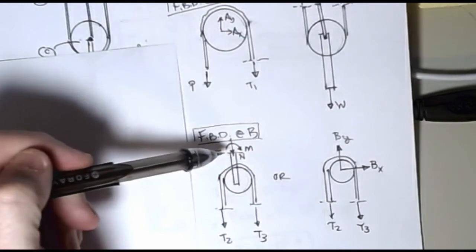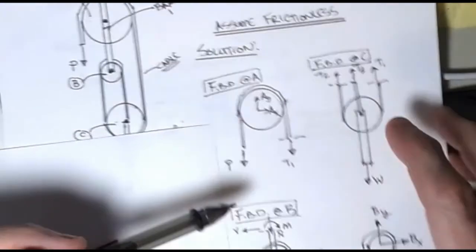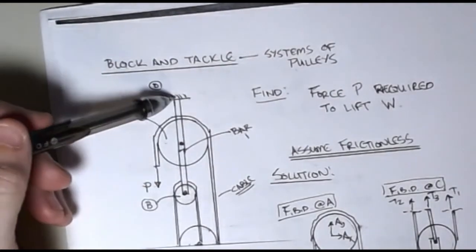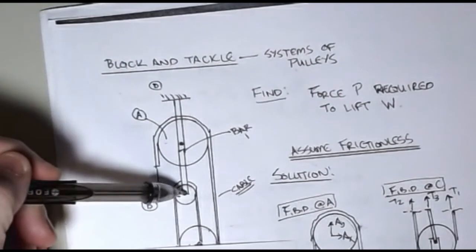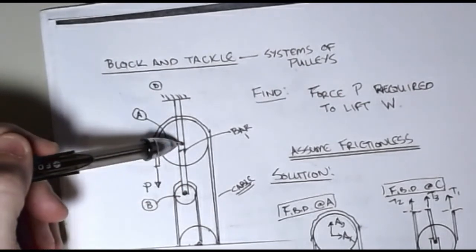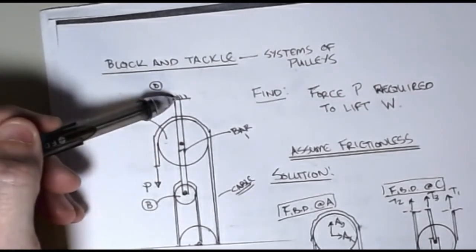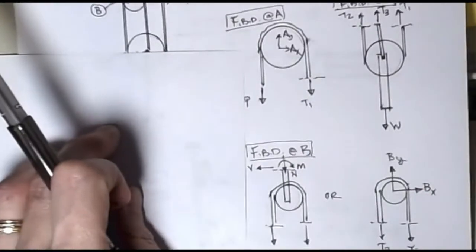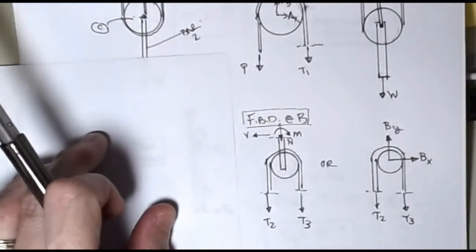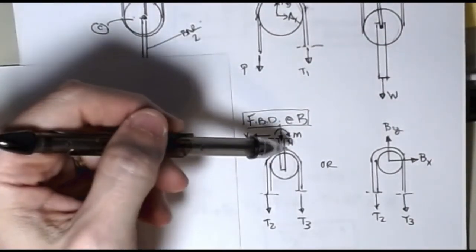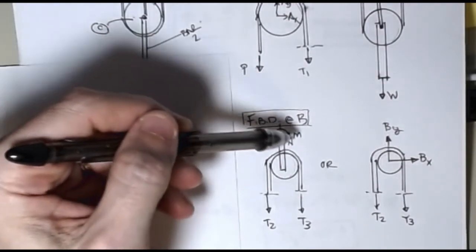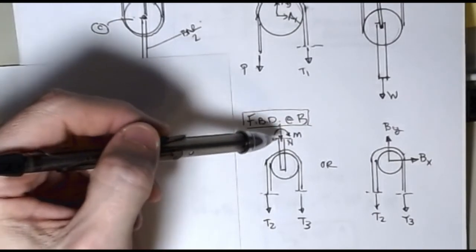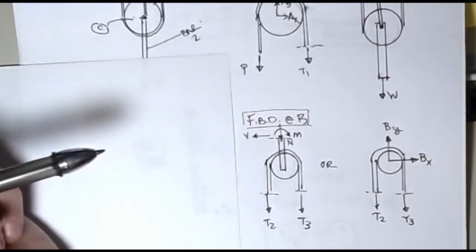But the problem is that the bar member, if you remember back up here, is a rather complex entity, right? It's not a two-force member because I have a pin here and a pin here, and then I also have a fixed connection here. So this thing is experiencing bending and doing all sorts of strange things, so I can't make any assumptions. And so I know we haven't talked about this yet, but when that happens, if I cut something, I always get three unknowns. I get an internal moment, I get a horizontal force, and I get a vertical force that shows up at the new cut location. So that's kind of an ugly little mess that just happened when I do that.